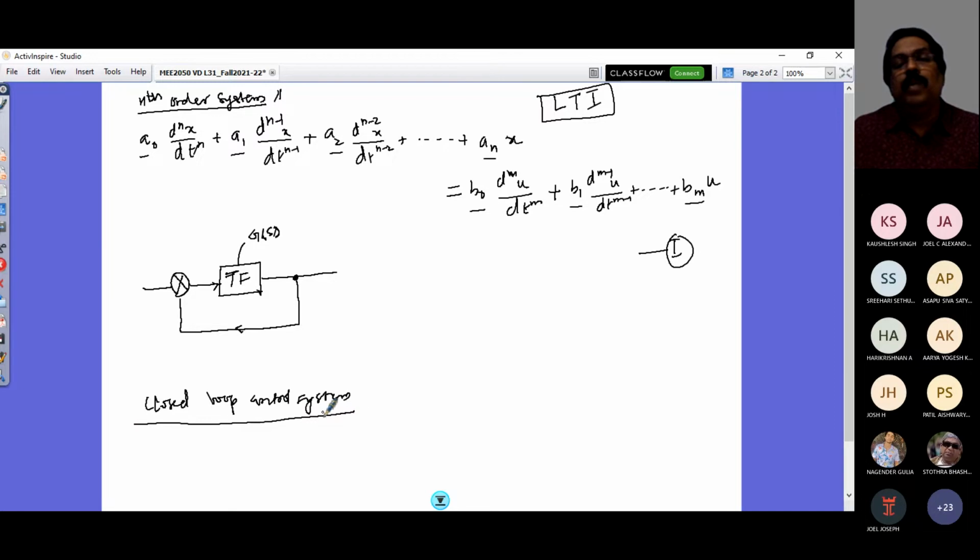Right. So what do we mean by a closed loop control system? If I look at my vehicle and it goes away from my path, in a case that we just have seen, where its behavior is understeer, I could correct by steering action. If it is an oversteer condition, then I counter steer and correct it. So I observe the output response and then do a corrective measure in my steering input. That is an example of a closed loop control system, right?